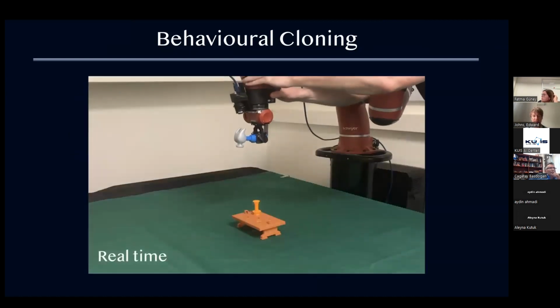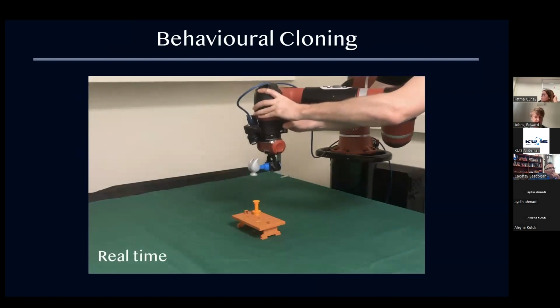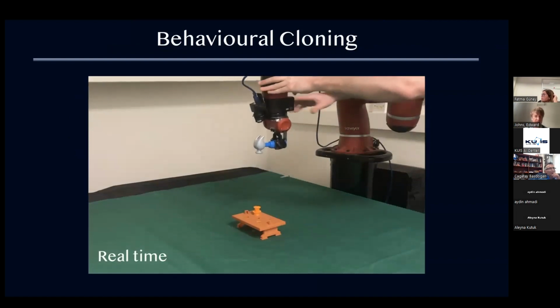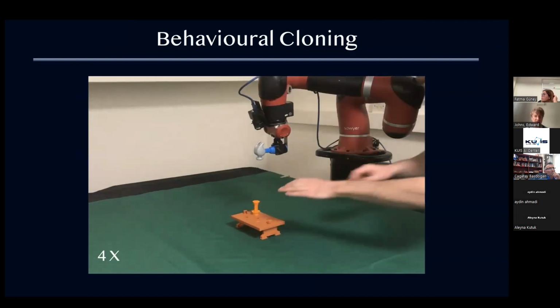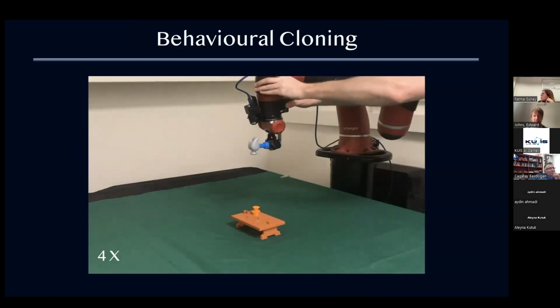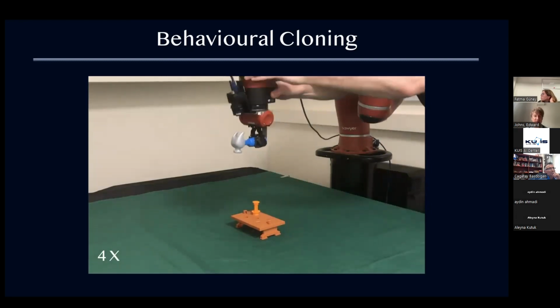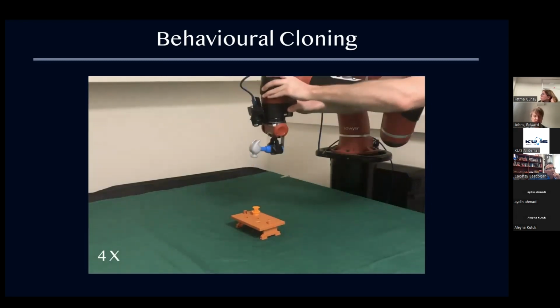In the real world, this is what this looks like. So this is me in my lab. And now I'm teaching the robot. The robot isn't exploring autonomously like with reinforcement learning, but I've still got to effectively keep resetting the environment and provide lots and lots of demonstrations. So it's still quite laborious. It's a little bit less laborious than reinforcement learning, but you still typically, with behavioral cloning, have to provide a lot of demonstrations. You would probably have to provide over 100 demonstrations for this task.